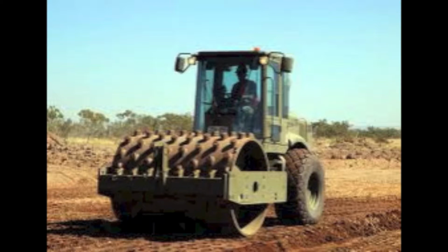A roller compactor is common on all job sites. This type of machinery compacts engineered fill to enhance soil characteristics. This is vital for solidifying a foundation or roadway. A roller compactor densifies soil by expelling the air voids and even rearranging soil particles into a denser condition.